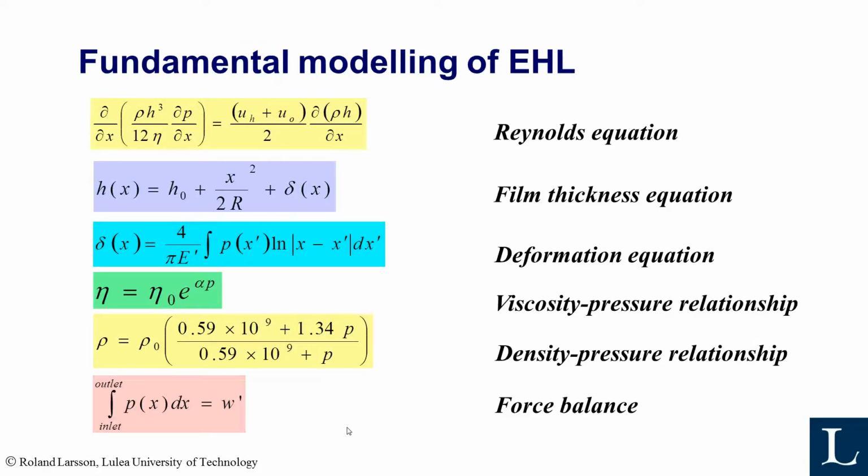So over the years, people have tried to simulate the EHL contact. We have also done the measurements, as you saw in the optical interferometry. The optical interferometry has helped us very much to understand how the film is formed and how it looks like. But you also need simulations to be able to compute the thickness for various combinations of these parameters. And when you do that, you actually solve Reynolds equation. You remember that from lubrication theory.